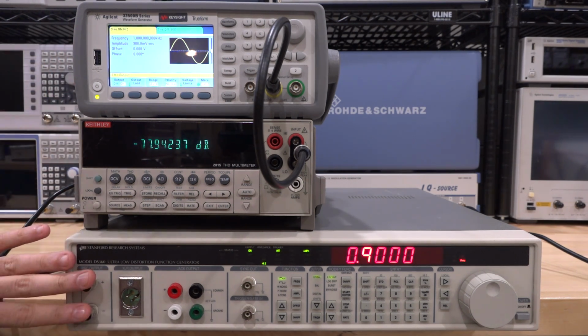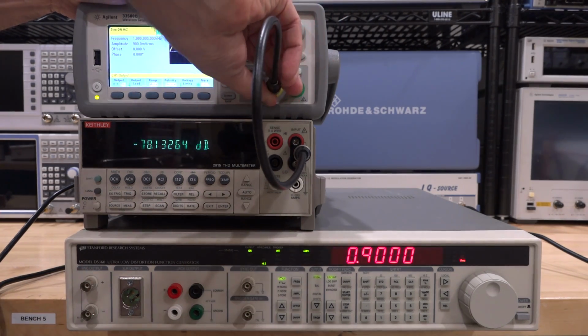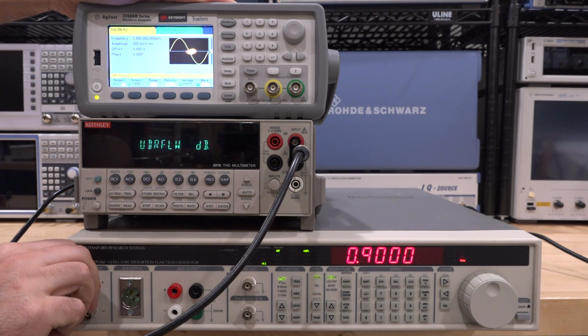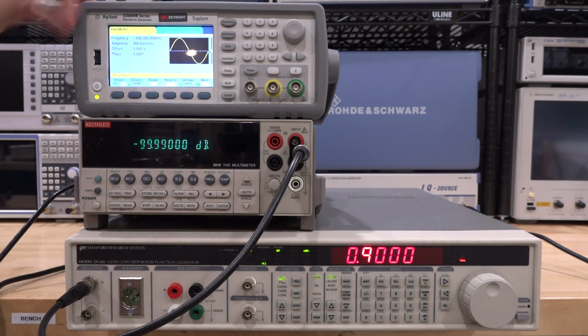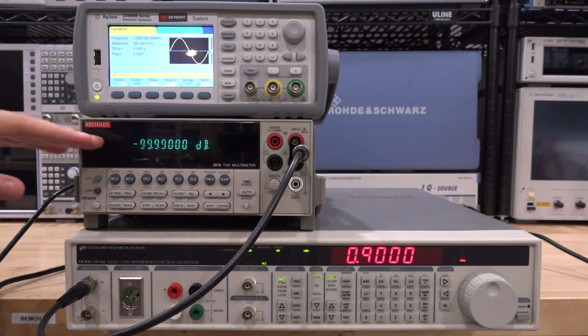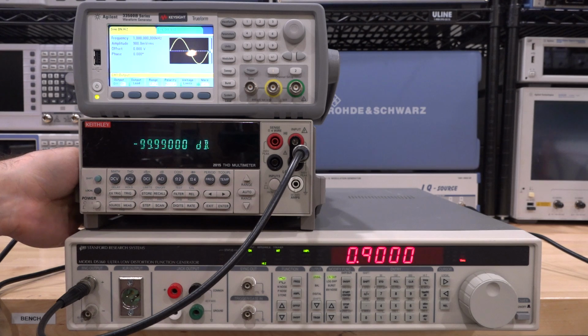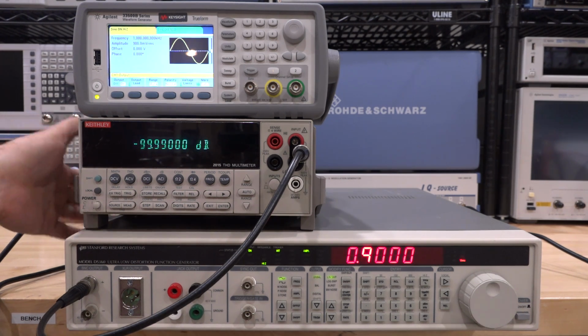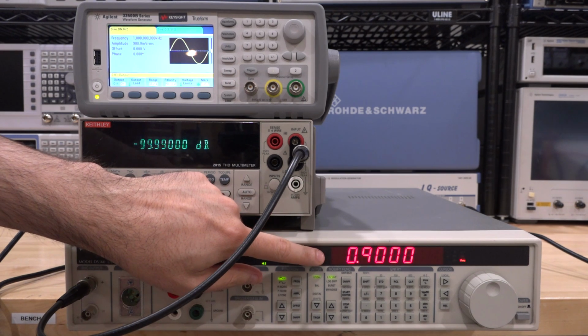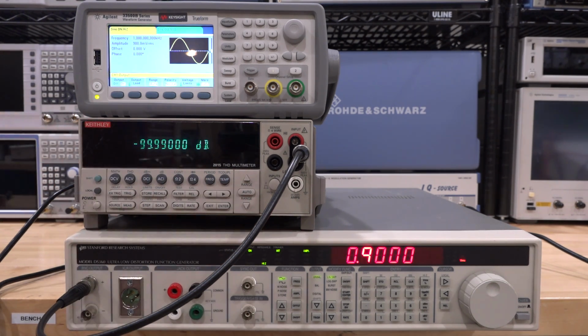Now I have the Stanford Research set to exactly the same settings. I'm just going to move that from here. Same settings, everything. We're going into the positive output here. It doesn't matter which one you go to. Look at that. It basically maxes this out. -99.99 seems to be the lowest value it can display. Anyway, so we're already at the floor of the 2015 THD. So we really do have to find another way to make sure that this thing meets the spec. At this condition, this should be about -110.